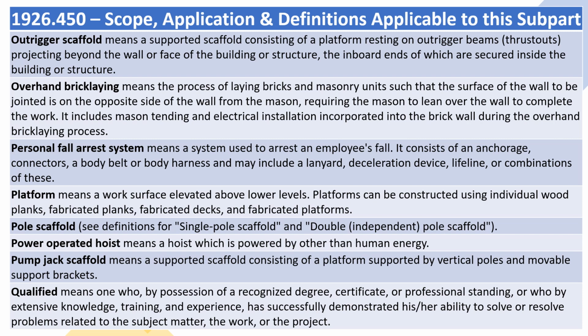Platform means a work surface elevated above lower levels. Platforms can be constructed using individual wood planks, fabricated decks, and fabricated platforms. Pole scaffold, see definitions for single pole scaffold and double (independent) pole scaffold. Power-operated hoist means a hoist which is powered by other than human energy. Pump jack scaffold means a supported scaffold consisting of a platform supported by vertical poles and movable support brackets.